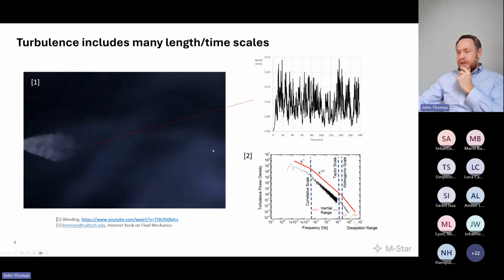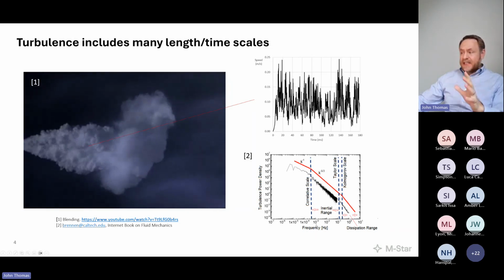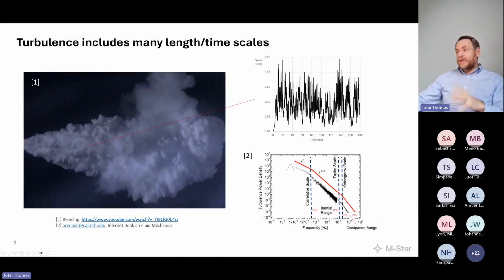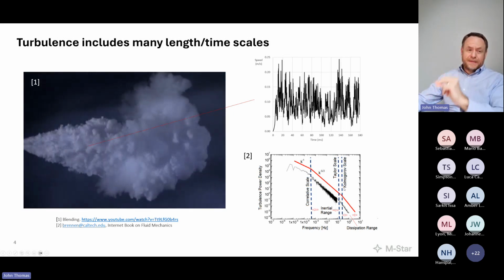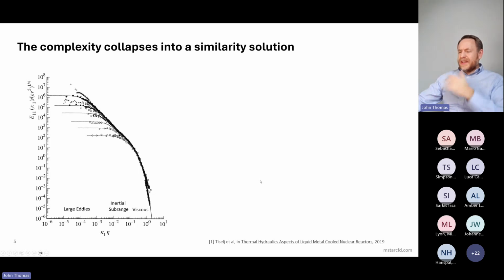And we'll see here that for a given turbulent system, these frequencies may be system dependent. But if we normalize by these intrinsic timescales, all turbulent systems collapse onto the same distribution. So here's what that looks like. If we normalize by, say, the Kolmogorov length scale, which can be calculated from the Reynolds number or energy dissipation rate, viscosity, or whatnot, then we get the same general energy distribution shape for each individual turbulent system. The integral of this, of course, will be the total energy in the system, the integral of energy over wave number.